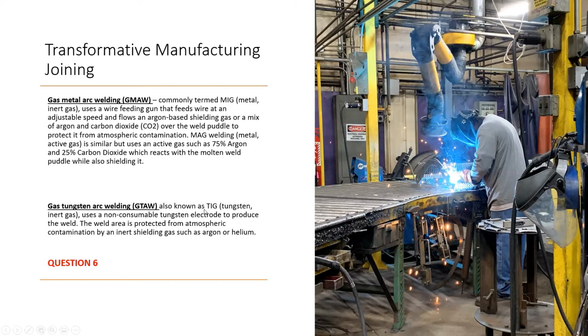Advantages, disadvantages to both. TIG welding doesn't typically give you the burn marks like MIG welding does. So sometimes if you have really, really aggressive welding, you can actually see burn marks poke through even after it's been coated. So to avoid that in some cases, if you have pieces that are showing very visibly, you would try and use a TIG weld in that situation.